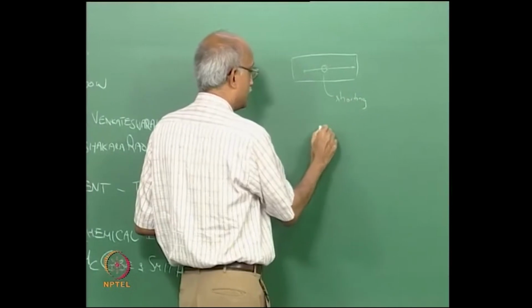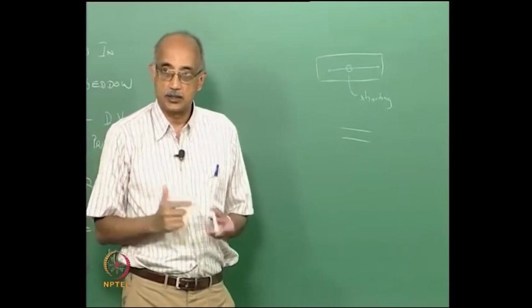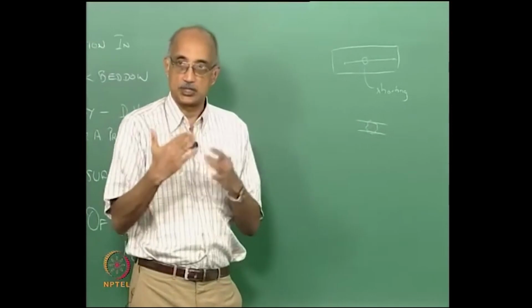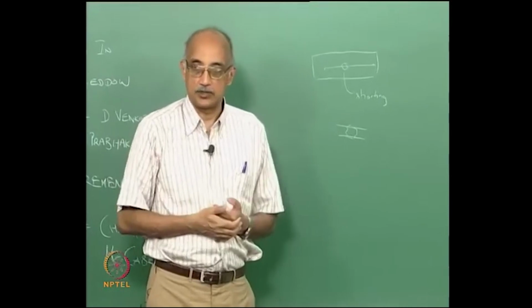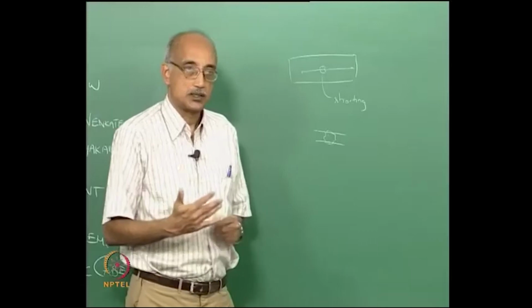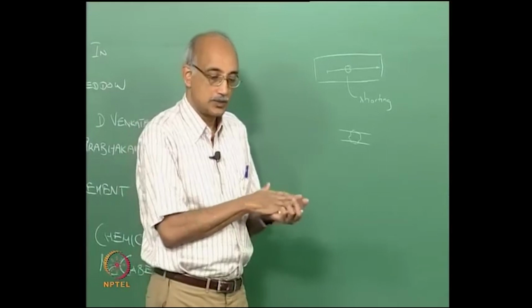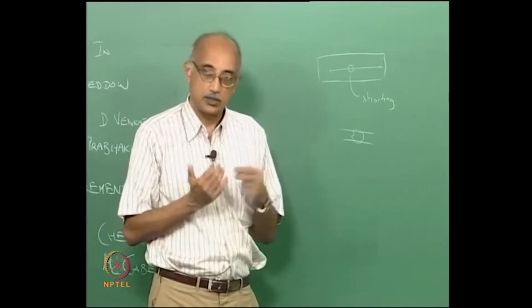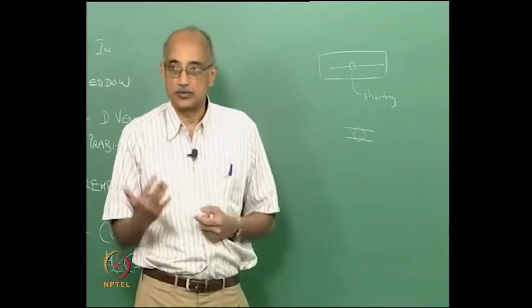or alternatively, if you have 2 parallel paths which are designed to be non-conducting and you get a conducting particle deposit so that it bridges those paths, then you get a conductive path which is going to interfere again with the functionality of the device. Now, if this phenomenon is instantaneous, in other words, the particle comes, sticks to the surface and then is removed, then there is no long term consequence of the particle. It may cause a yield loss in your manufacturing line, but may not cause a reliability hit in the field.